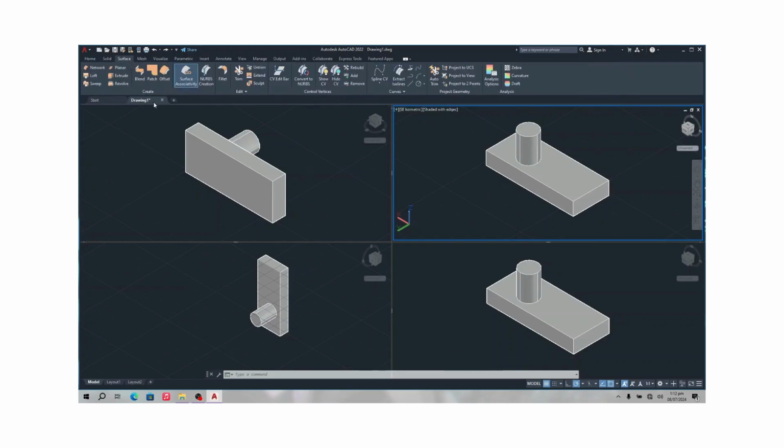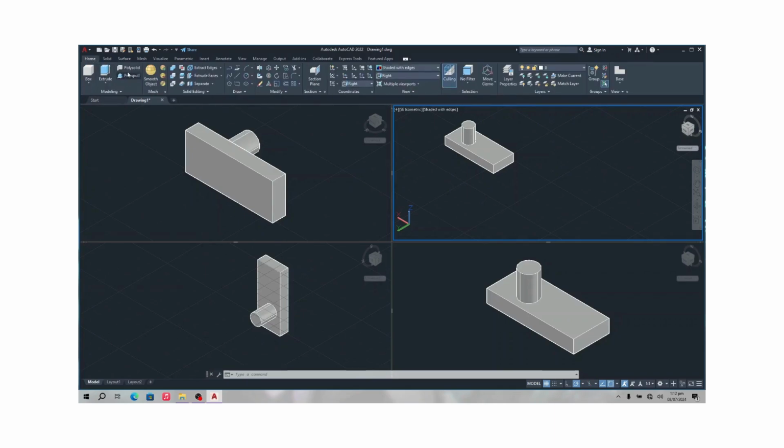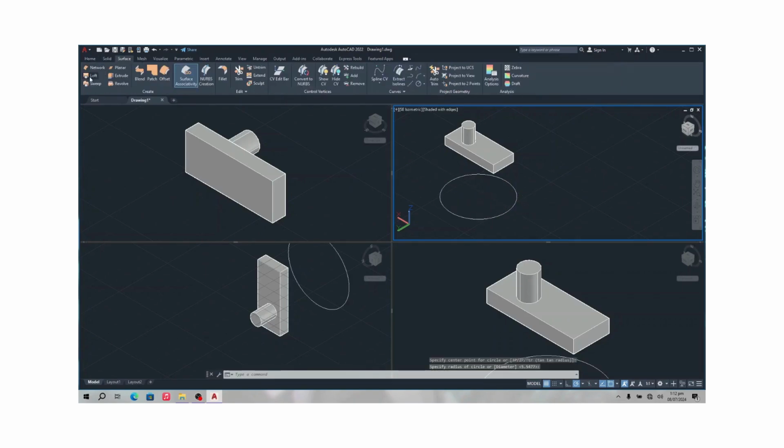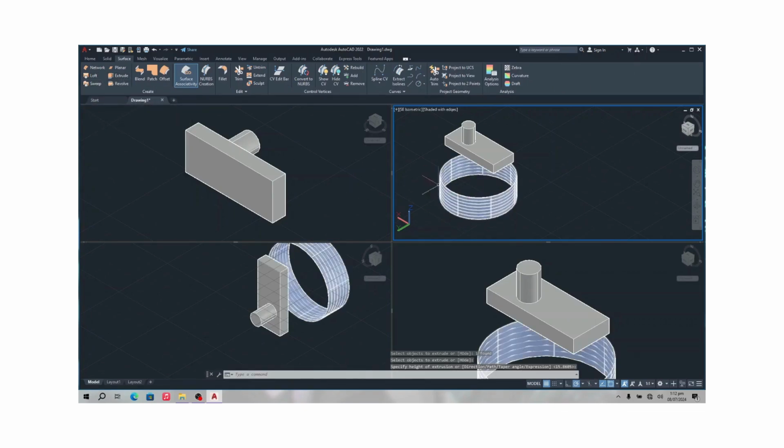After that we have surface tools as well, which are basically making sheet surfaces which you can cut and change, like hollow spheres, hollow cylinders and stuff like that, because these things are a bit different. Surfaces are different since they make them hollow. So if I make a circle here, go to surface and make an extrude on this circle, it will be hollow like this.